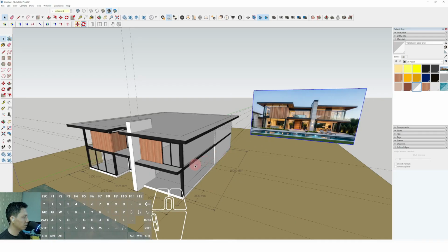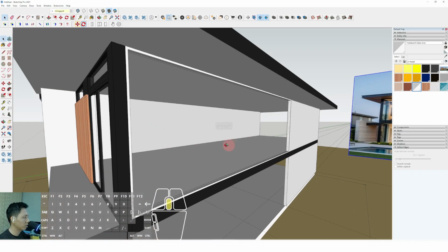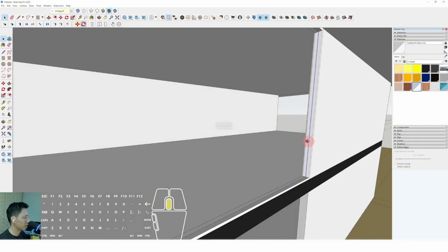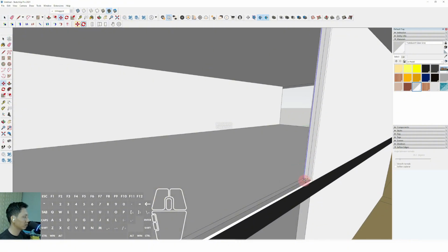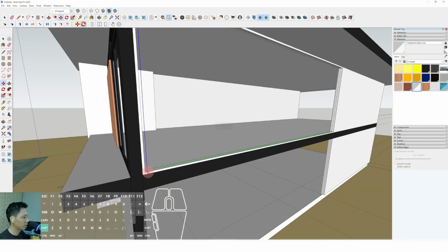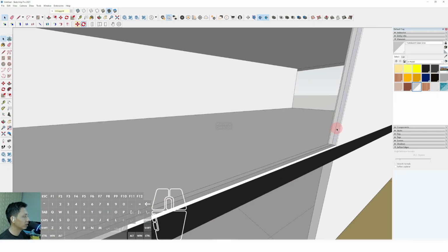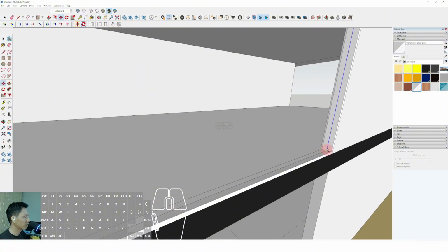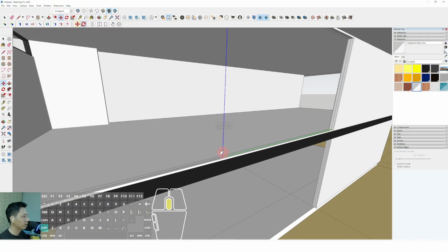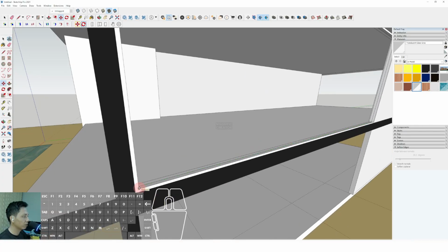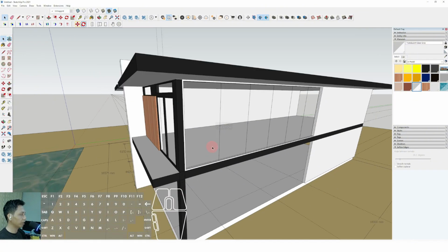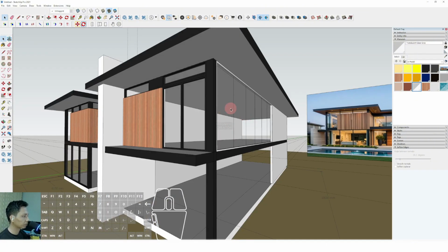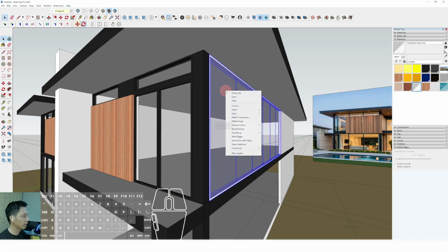Okay, just like this. I will move it first. I will move it in this first. Okay, we can click this line, select move, tap control, click from this line until this position. Then I'll repeat. We can click this line, select move, tap control, click from this line and place to this position. Then we can type 6/ and enter. It will be divided automatically. Then we can triple click, right click, and make group.